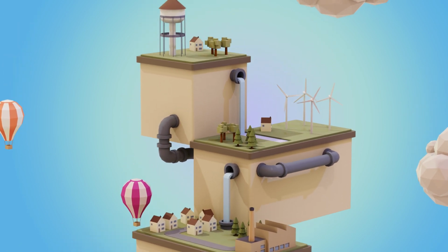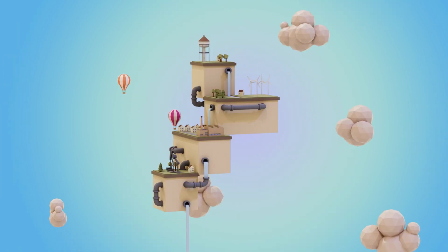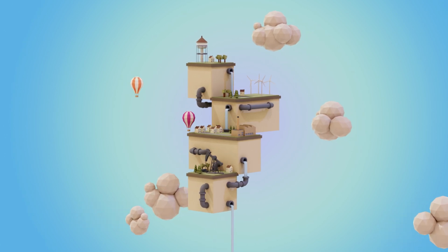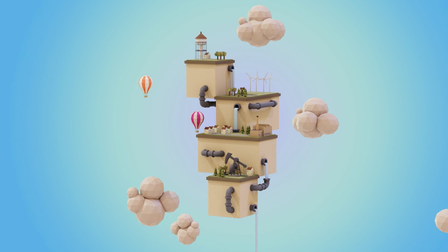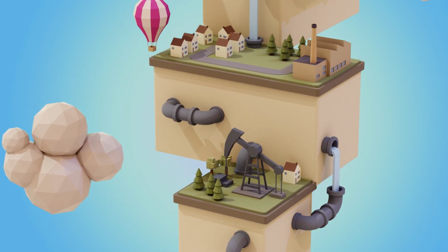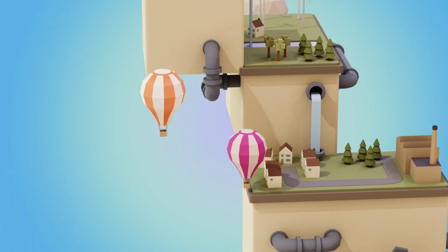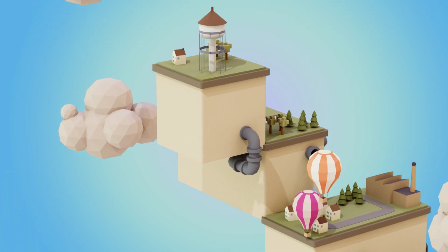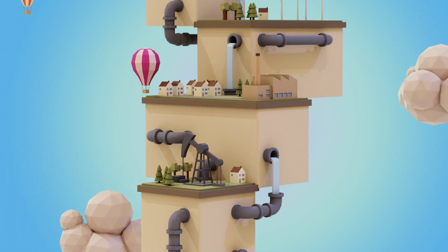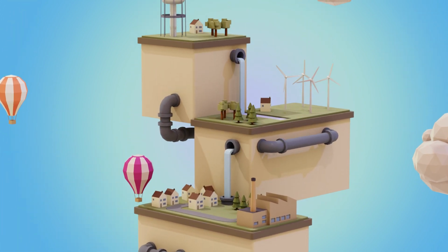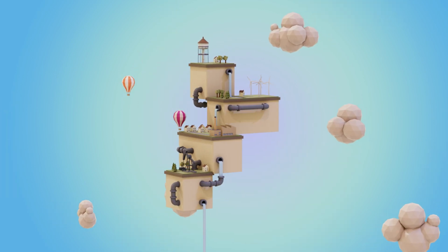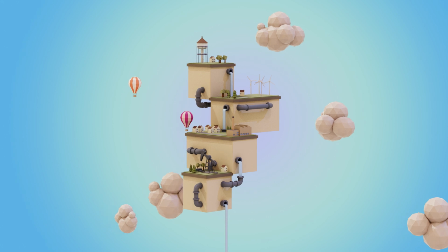I would say there's 2 stages to creating low poly work. The first is to get your basic shapes and your basic scene, so block out as it were, and then the next stage is to add the minor details. So let's say with these small houses that are in this scene, just put them in as cubes to start with, and then you can make them into a house in the second stage. But it can be frustrating if you've added a few details to an object and then you realise it's the wrong shape, size, and you have to adjust those details. So get your basic scene set up first, then do the details.